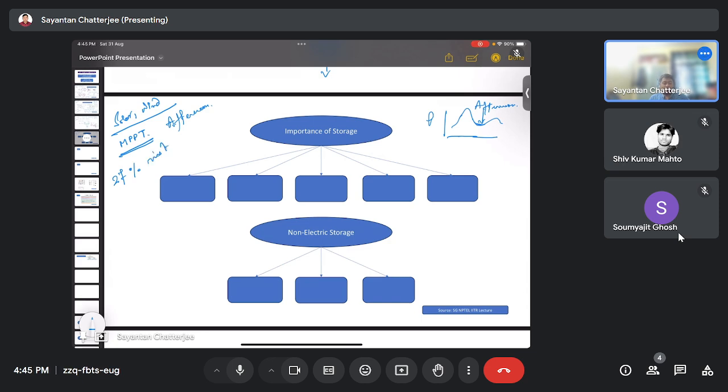That is the installed capacity, right? Out of this 27% installed capacity, at a point of time we only have around 12 to 13% instantaneous percentage share of solar. So although we have 27%, at any point of time we can't exceed this value of 12 to 13% of solar generation participating directly in load sharing. Although we have a high installed capacity, only about half of that can participate each time, because the solar insolation is not the same all over our country, India. I'm talking about the Indian context.